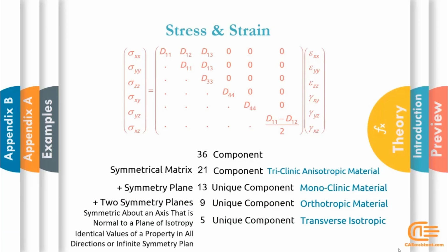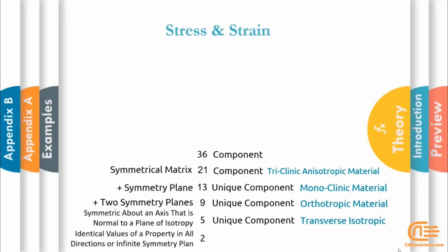Finally, an isotropic material is uniform in all orientations and has 2 constants. In this tutorial, we will look at some examples of isotropic and orthotropic materials. To do this, we examine the stiffness matrix and Jacobian for the isotropic material.